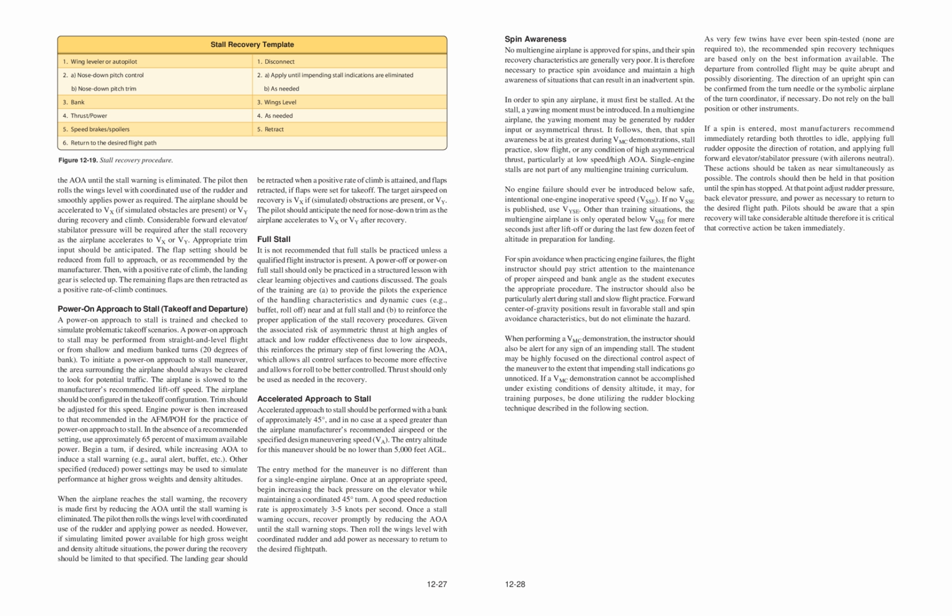The flap settings should be reduced from full to approach, or as recommended by the manufacturer. Then, with a positive rate of climb, the landing gear is selected up. The remaining flaps are then retracted as a positive rate of climb continues.